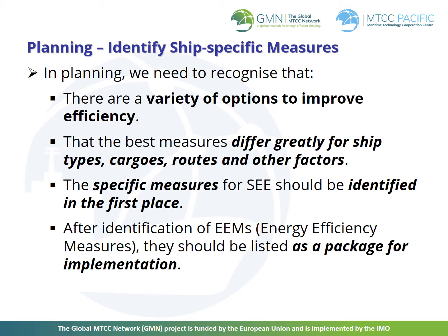It is recommended that the specific energy efficiency measures for each ship need to be defined. To do this, there will be a need for carrying out activities such as energy audits or energy reviews for the corresponding ship. The SEEMP should be adjusted to the characteristics and needs of individual companies and ships, and therefore each ship will have its own ship-specific plan.